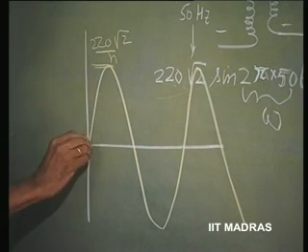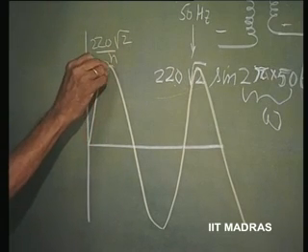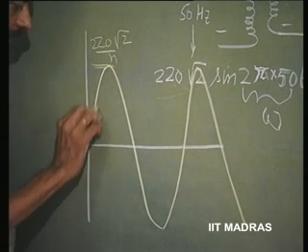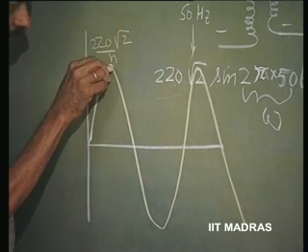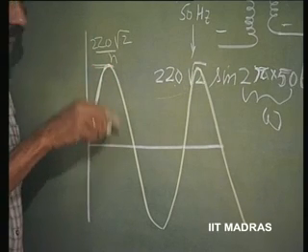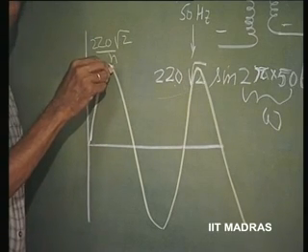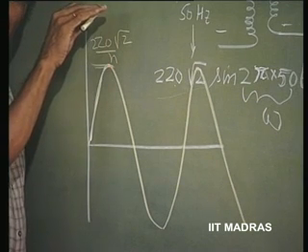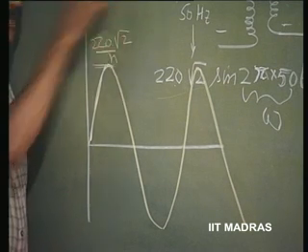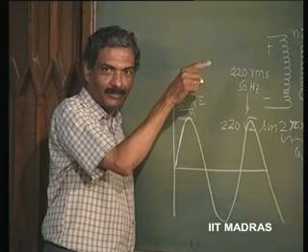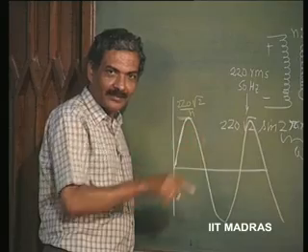It will charge at t equal to 0, let us say it was not charged, it will charge up to this point, then it will try to discharge, because this voltage has gone below the capacitor voltage. But the voltage here might not have gone down at all, it has remained almost the same. So, immediately the diode will conduct, the capacitor will charge to the input voltage,